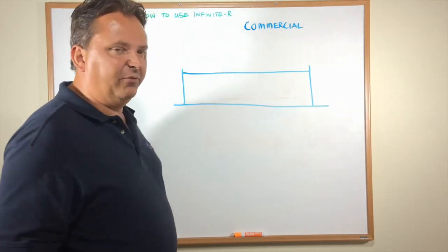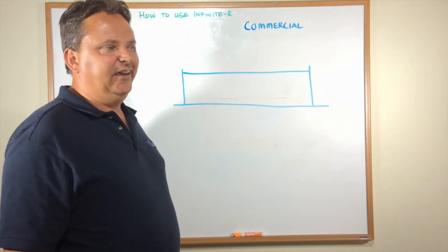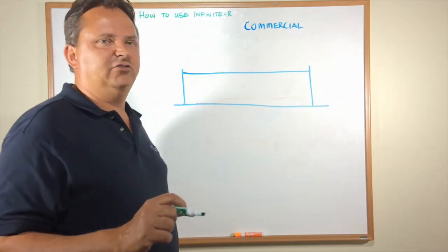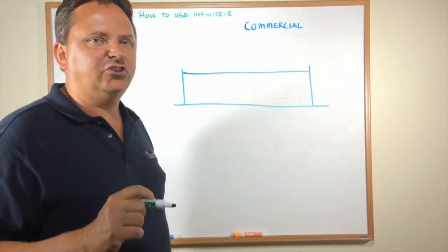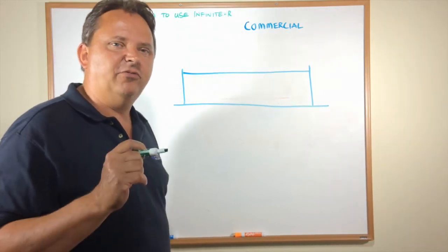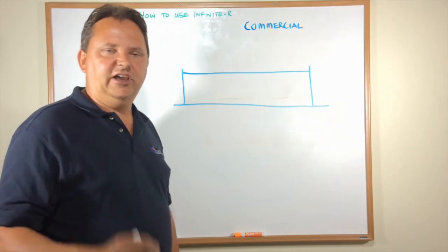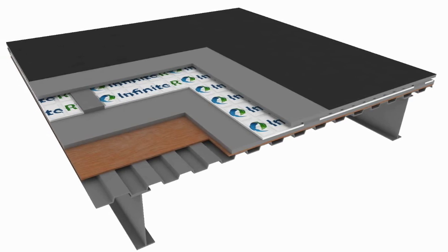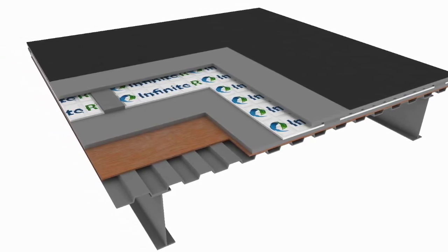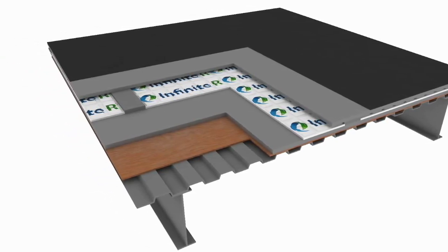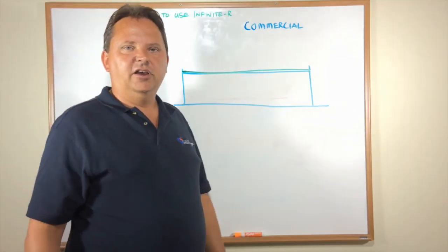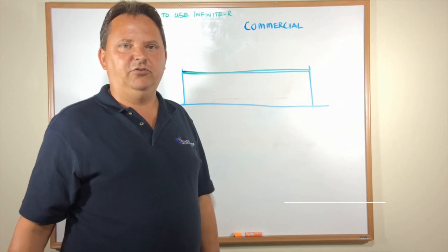But in general, what we see with roof designs is about a 3 BTU per hour average over the summer months of reduction in heat flux through a roof with phase change over a standard roof. So imagine that we would put this material in the roof structure of, say, a Walmart. Let's say it's the average large Walmart, about 330 thousand square feet of floor space.